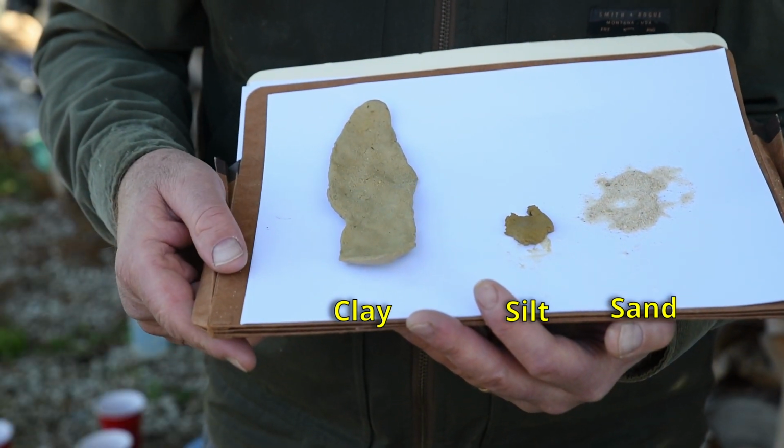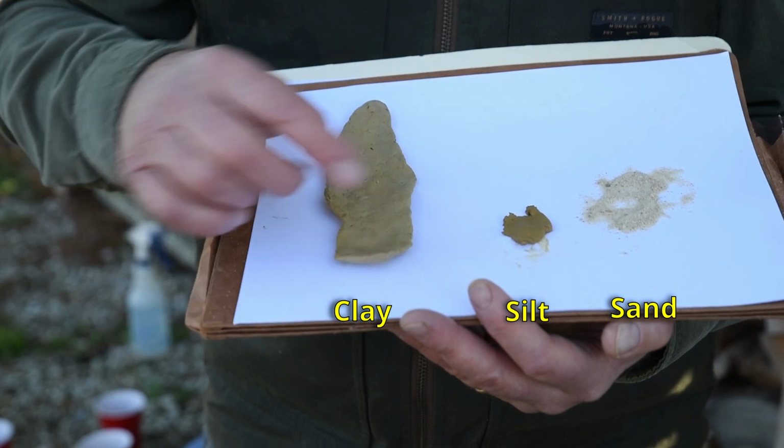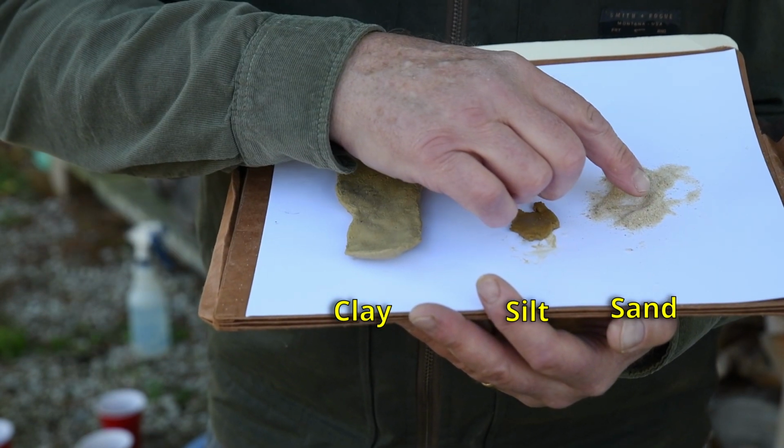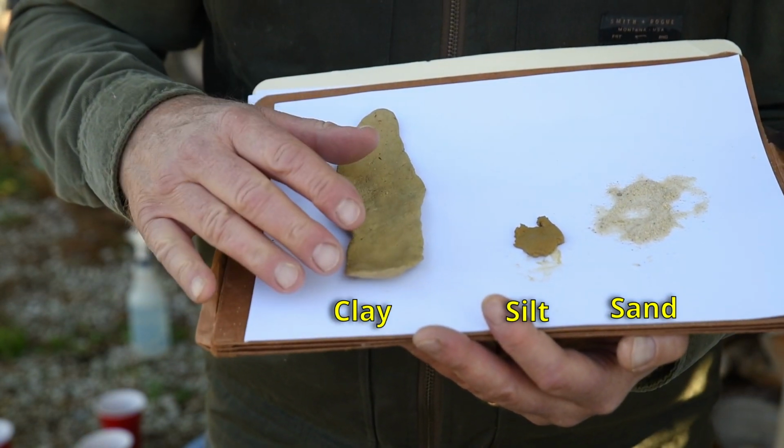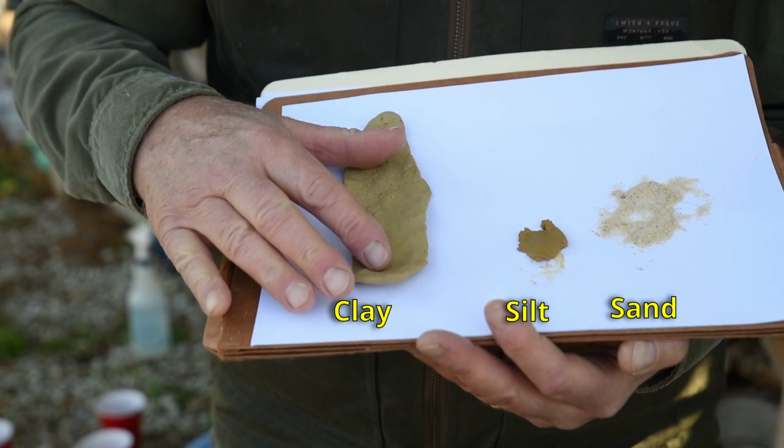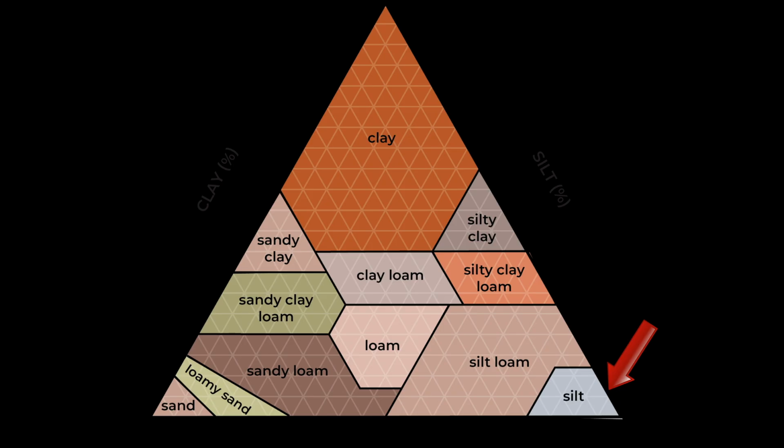We're going to need quite a bit of rock to armor the spillway when building out of silt or building out of sand. And if you build your spillway on a gradual slope out of clay, you won't need much rock. The presence of silt should be a huge warning sign to anyone wanting to build a wetland. Silt does not have enough clay to compact or hold water. Silt is highly erodible, so a stream flowing over silt is likely to cause major head cuts and serious erosion.